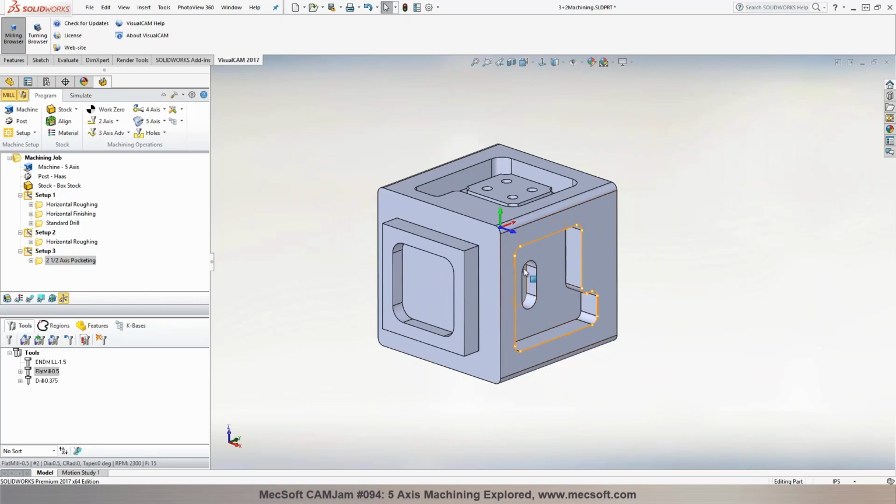Once you have all of these programmed, you have your post. We would need to provide you a 5-axis post. We would need to develop one based on a machine configuration, so we can take one of the existing 3-axis posts and update it to 5-axis. Once you have it set up in here, right-click and do a post all. It will post and compute the angles for each of these orientations. Wow. Okay, so that will make everything easy.